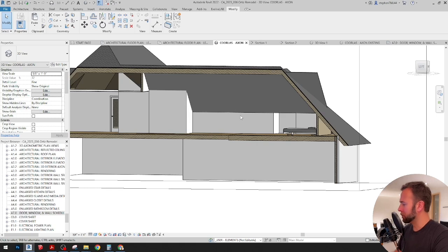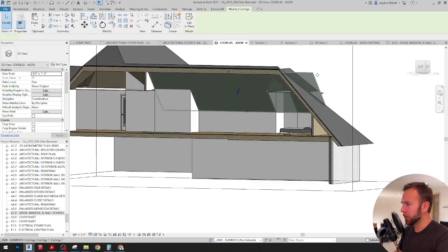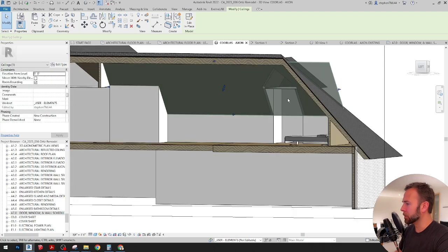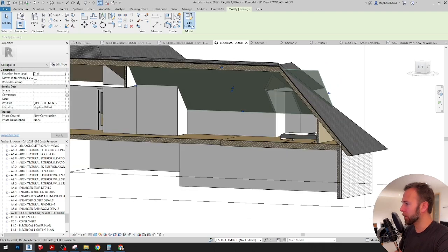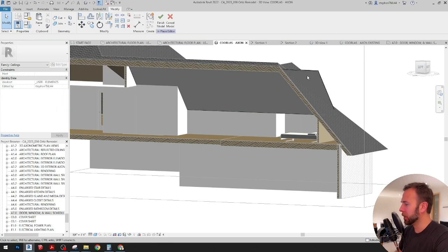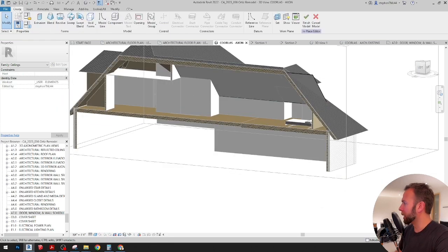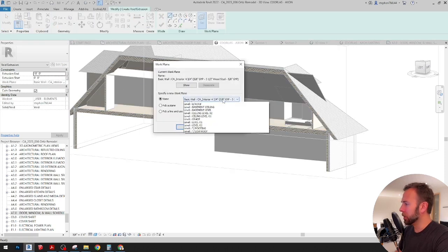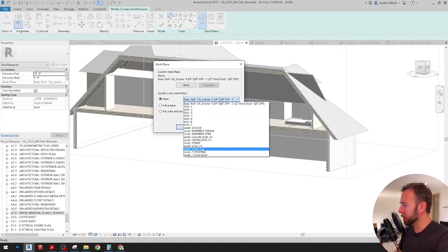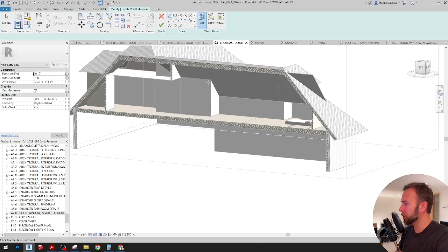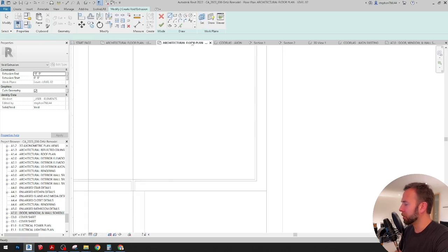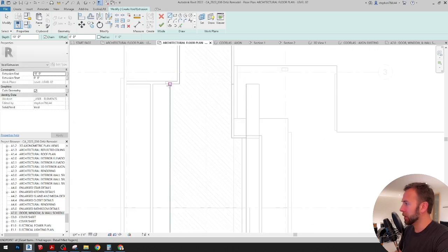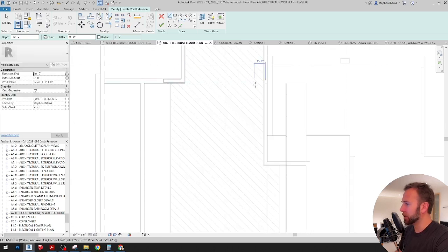Okay, so like I said, I've got the generic ceiling here, and now we can start to do some void cutouts. So just to show you what that looks like, if I go in and edit my model, create void extrusions, make sure it's set to a decent work plane here, like level 2, okay. We'll do the vertical cuts first, go to our floor plan, and I had set the work plane for the ceiling at this wall plane here.